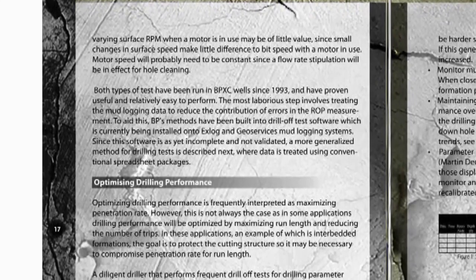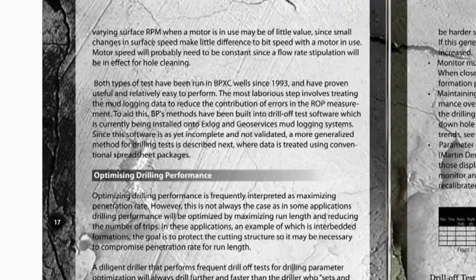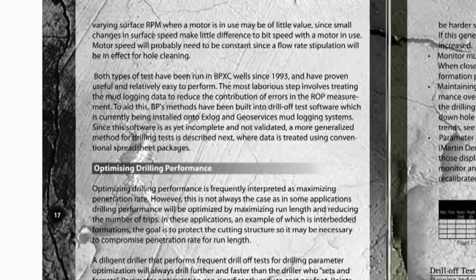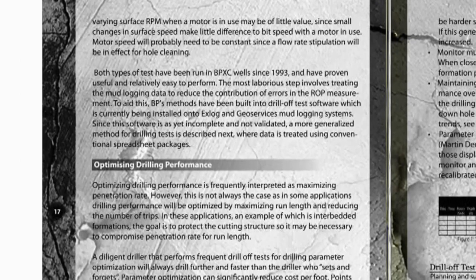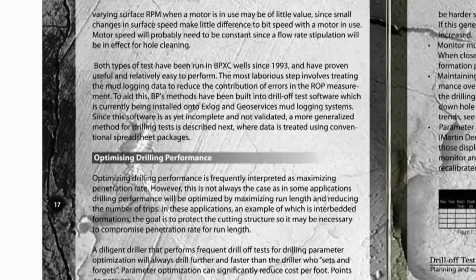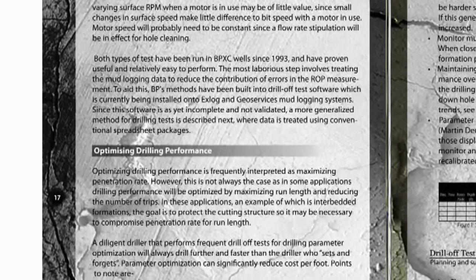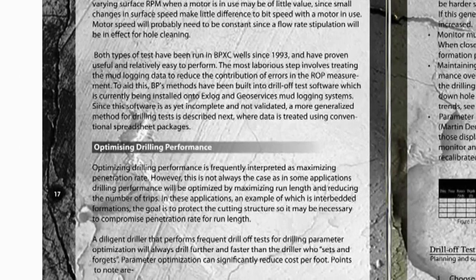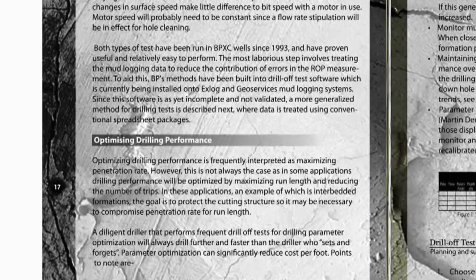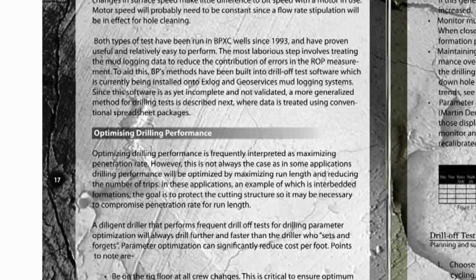Both types of test have been run in BPXC wells since 1993 and have proven useful and relatively easy to perform. The most laborious step involves treating the mud logging data to reduce the contribution of errors in the ROP measurement. To aid this, BP's methods have been built into drill-off test software, which is currently being installed onto Xlog and GeoServices mud logging systems. Since this software is as yet incomplete and not validated, a more generalized method for drilling tests is described next, where data is treated using conventional spreadsheet packages.